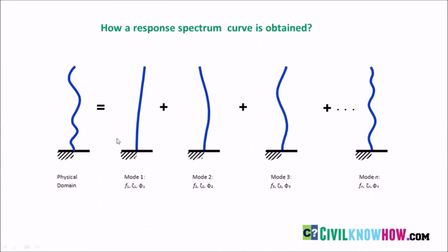Let's assume our structure to be a single straight line. When the seismic acceleration is applied on each joint of the model with respect to a single degree of freedom, different mode cases with unique modal responses are obtained, that is, from mode 1 to n number of modes. In the response spectrum analysis, we combine all these modal cases to obtain a single response for the structure.